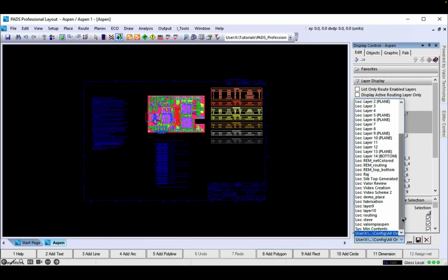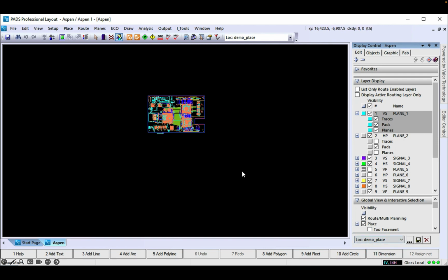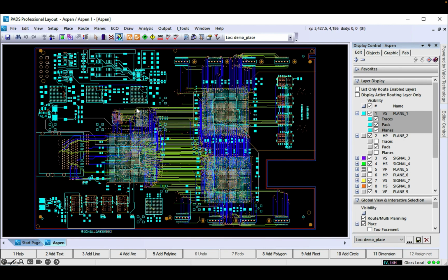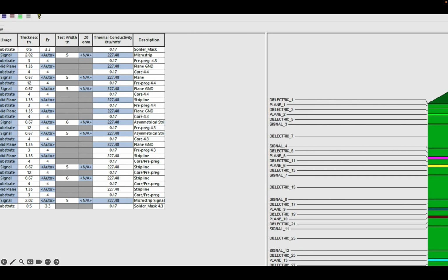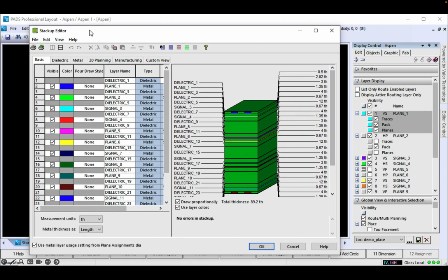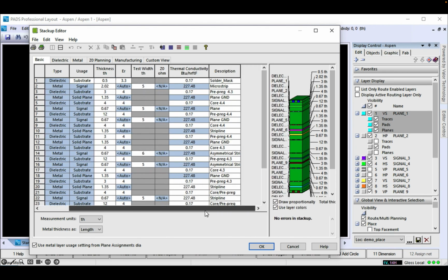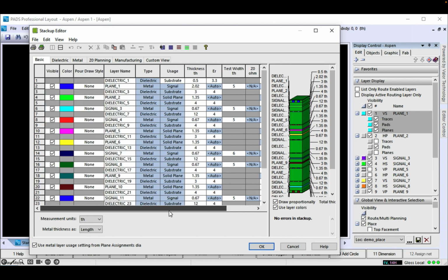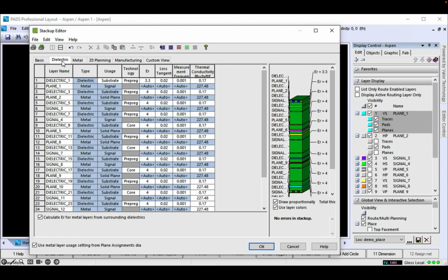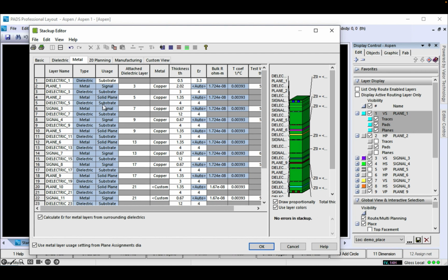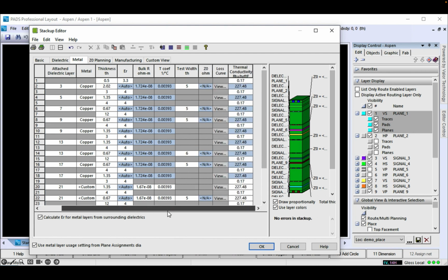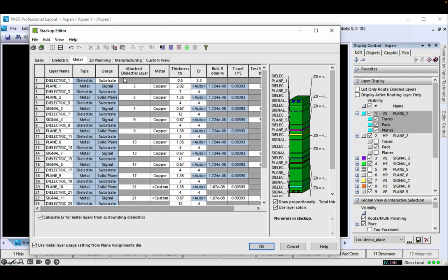First, let's have a quick look at the stackup, as it plays an important role in passing intelligent data into the PCBflow or Valor NPI engines. As you can see, the stackup includes material and dielectric thickness and copper widths, along with technology types, prepreg versus core. So there's nothing to do here but let the system assign the desired constraints rule set from the DFM profiles available within PCBflow.